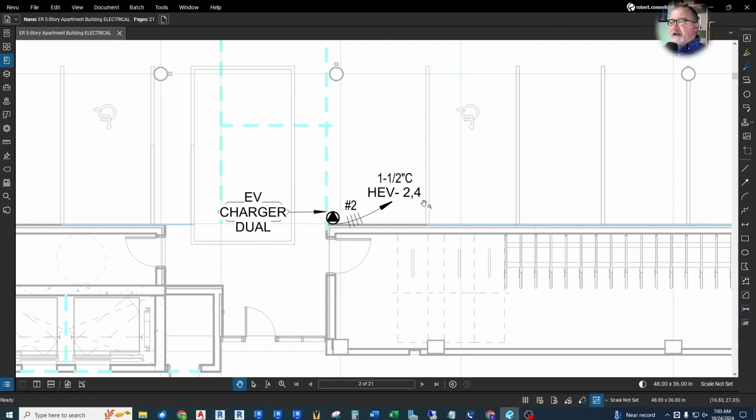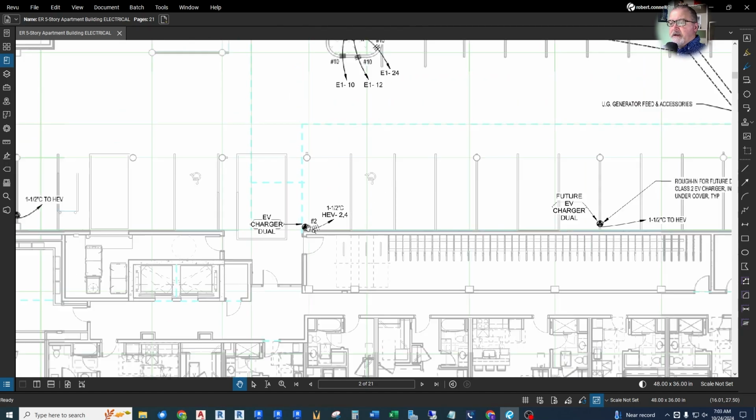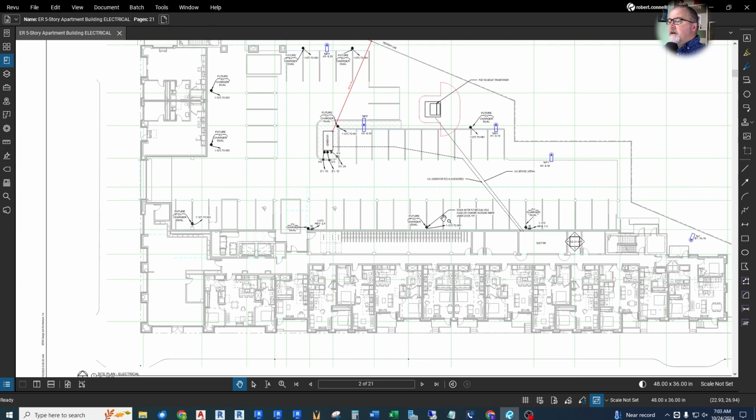This one here actually has wire in it. So we have the equipment connection. We have the panel circuit numbers. It's a 208 two-pole charge point. In fact, this building, we'll find out, is a 120/208 three-phase building. And it needs number 2 wires. So this is telling them a little more detail of what's needed, because it's not future. It actually goes in now. So that's what's showing out here.